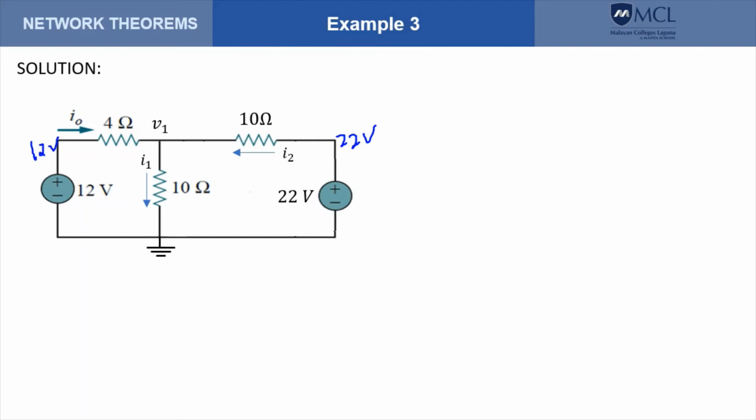So then we write a KCL equation. In nodal analysis we use Kirchhoff's current law. So we utilize this node to write our KCL. So current entering minus current leaving equals 0. So current entering that node, I sub naught and I sub 2, minus current leaving that node, which is I sub 1. We replace these currents by the node voltages.